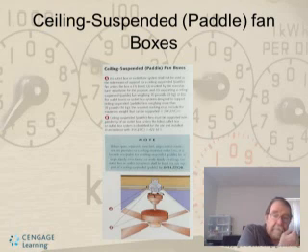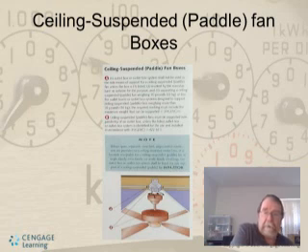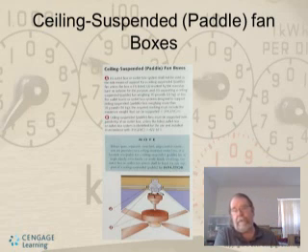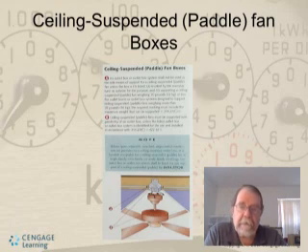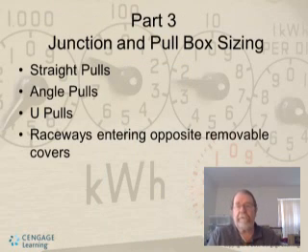So in other words, what they're saying is you need to make sure that you get a box that's rated, okay, and that can support these. I've seen some of these where people just mount it to a box that's sitting there inside the ceiling, and the only thing that's supporting the box is a bracket that they put up there or something, and sometimes that causes problems. Especially if the fan moves around a lot, eventually it'll fall.